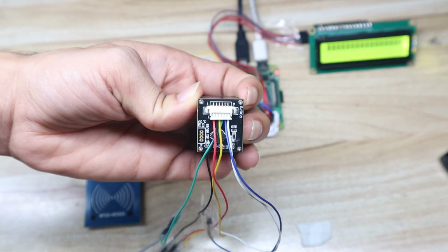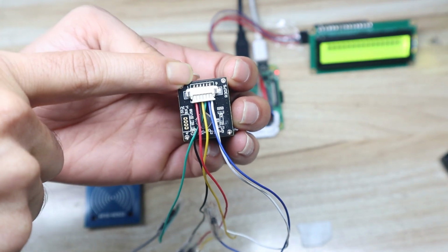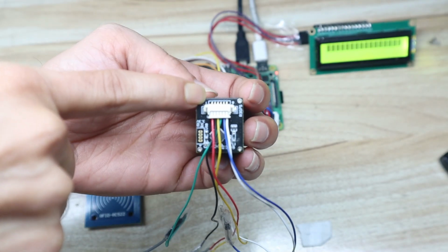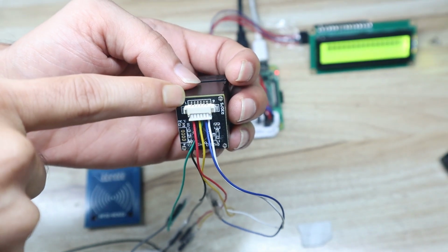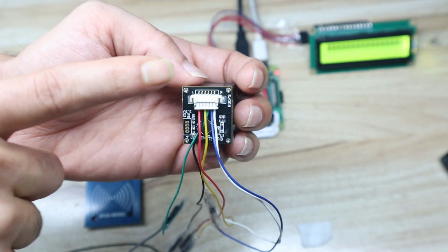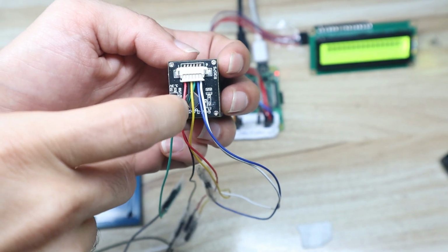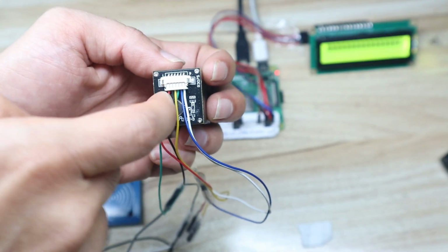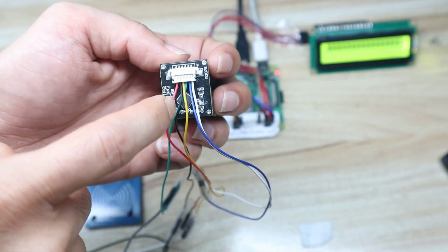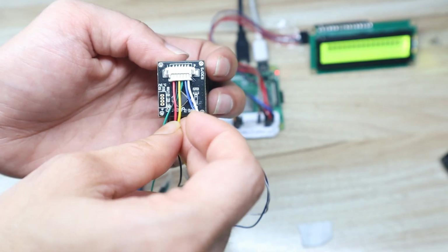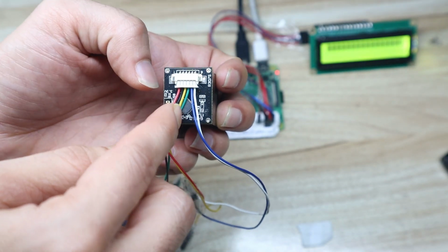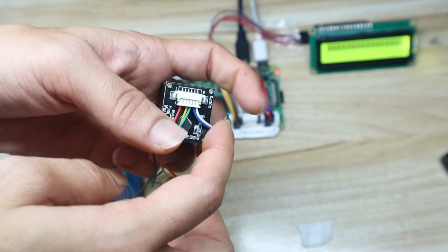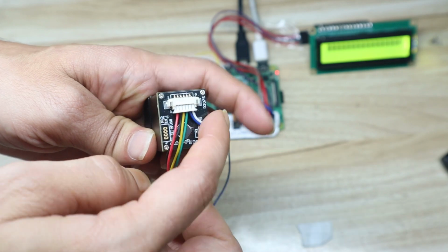Okay, so next hardware is fingerprint sensor module. So fingerprint sensor module, you can see there are pin number 1 to 6, but we are using only 4 pins. First pin you can identify with the number here, it is clearly mentioned 1 number here and 6 number here. Please focus here, at your end the color may be different, but the pin structure will be the same. So first pin is red pin, that is the VCC pin. Second is ground pin. Third is yellow pin, that is the TX pin of this sensor, and fourth is the green pin, that is the RX pin of this sensor. So we will only use these 4 pins. Okay, neglect the last 2 pins.